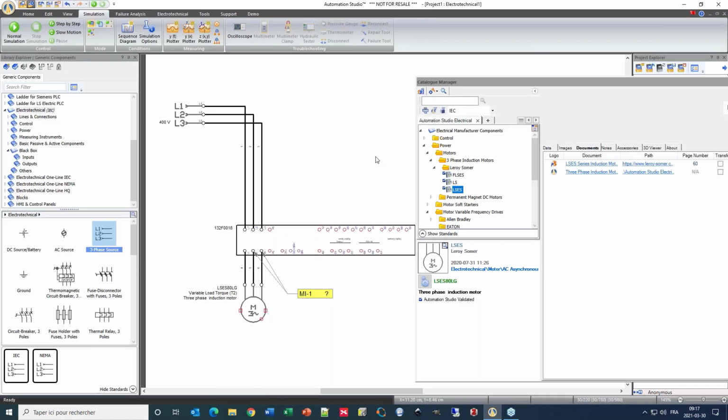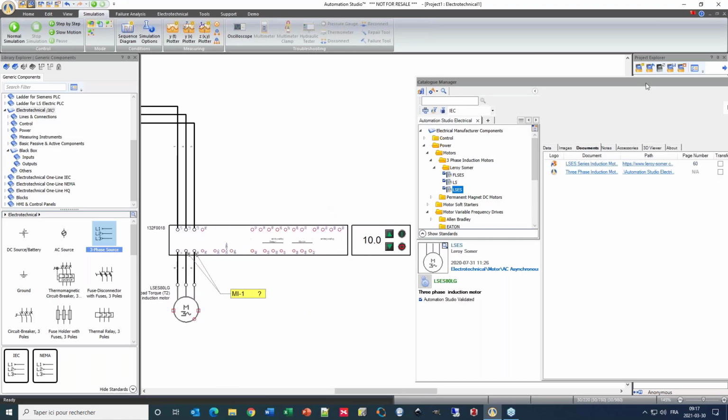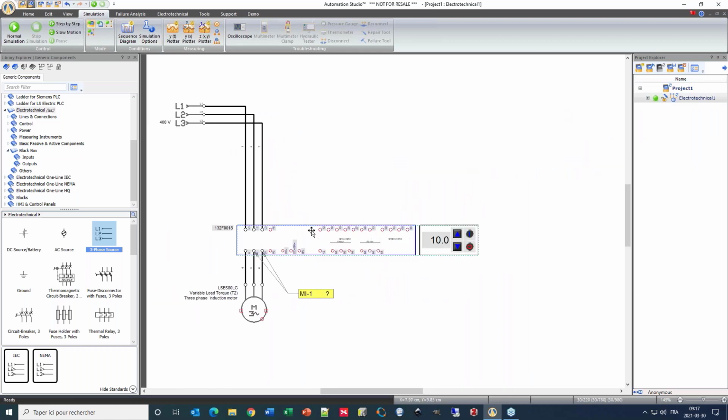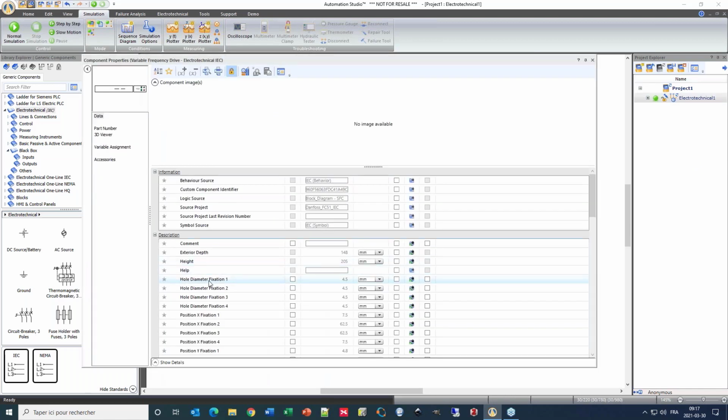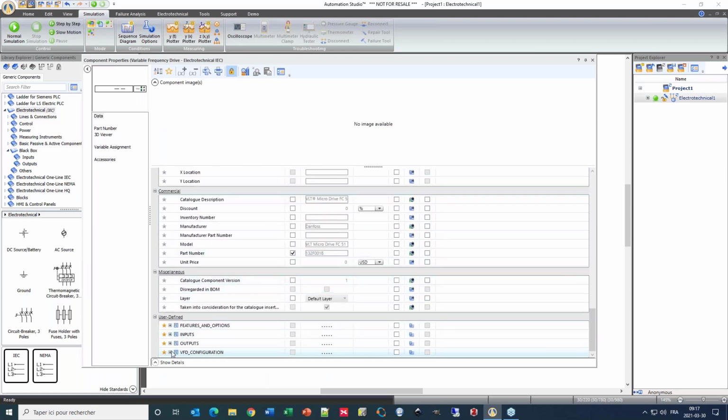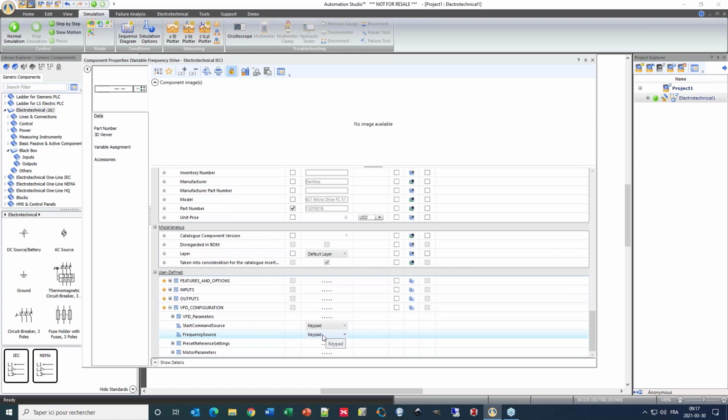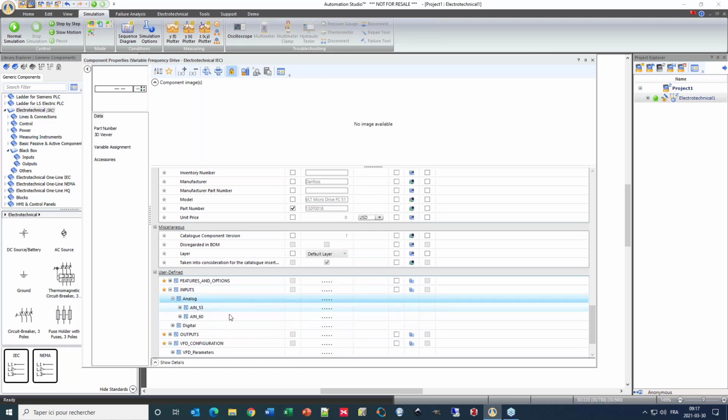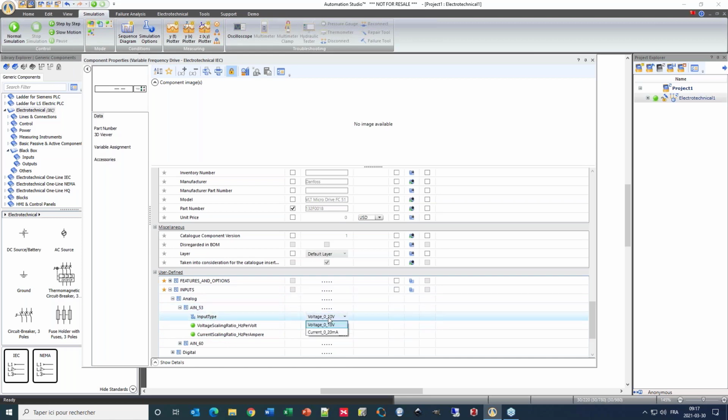Okay, so then I can also use it in a different mode. Let me just close that. I can go to my VFD parameters. As before, I can go completely down here and decide, instead of using the keypad as my frequency source, to use my analog input 53. I then have to make sure that my analog input 53 is connected, for instance, on a current input, which is configured with a scale ratio of 2500 between the hertz and the amps. Now I can close that window.